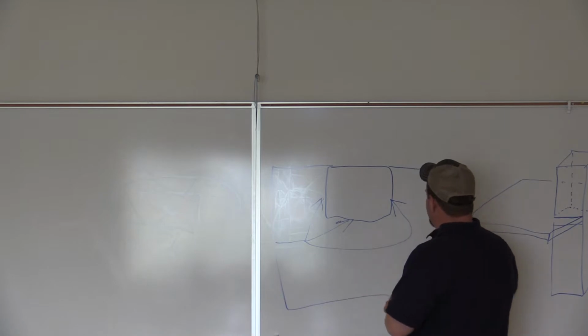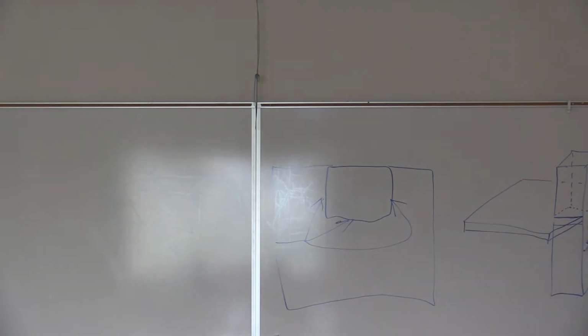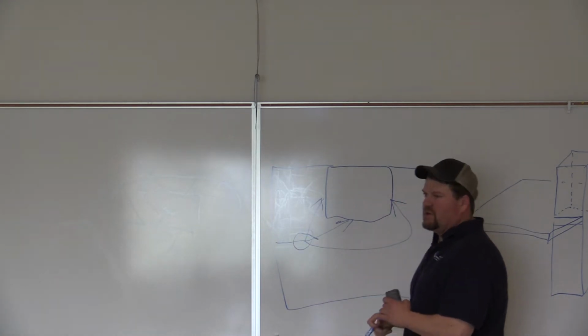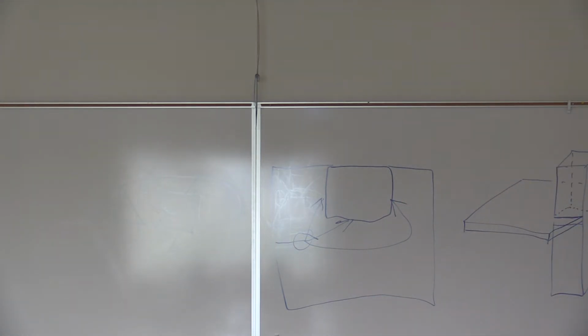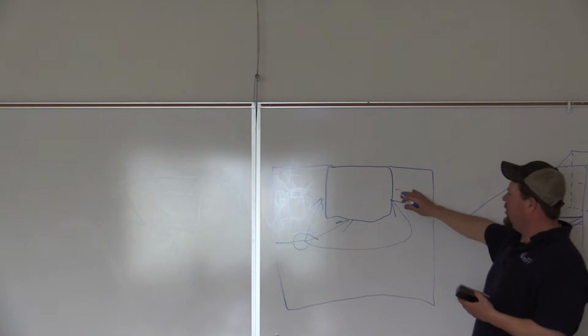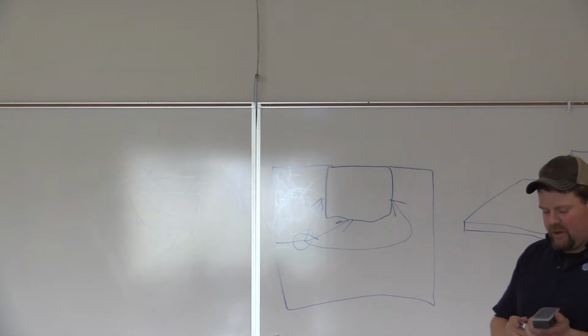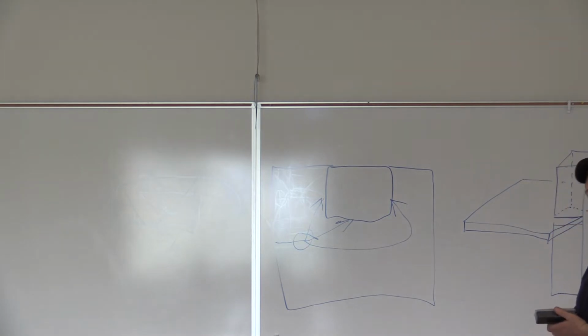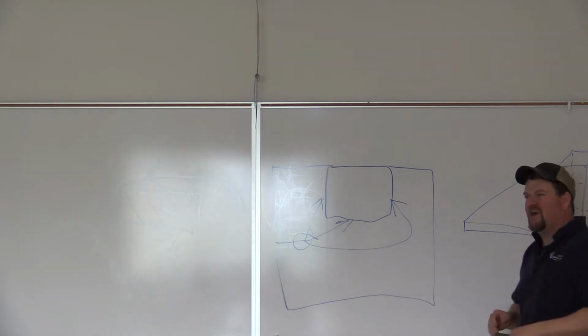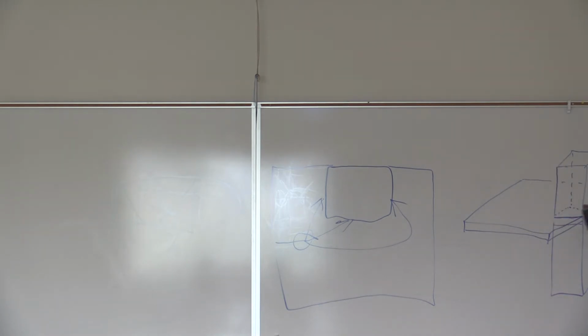And it's usually not going to break that way. But you can't weld this front face, right? So you can't use a weld all around symbol, because you don't want to go all the way around it. There's no reason to. So in this case, you can only weld this from 3 different directions. And that is typically when you'd see a multiple arrow situation. So if you see a multiple arrow situation, you got to look at your geometry. It might be a little more complex than you thought. Or just say, oh yeah, all the way around that thing is unacceptable. I can't really do that.